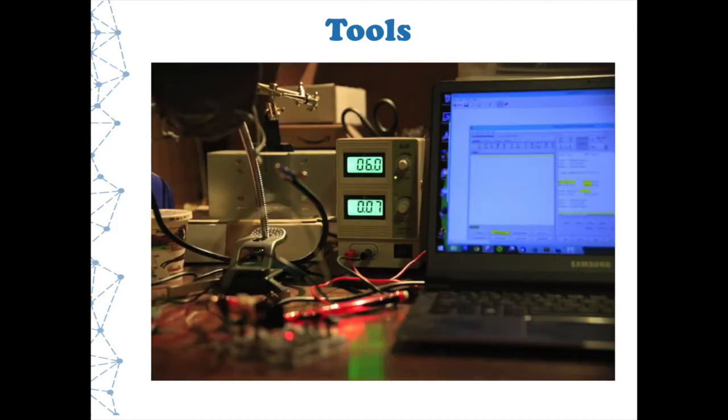Things like a variable power supply, all these little things, they're not required, but they help. They make what you do go much faster and give you flexibility that you would otherwise struggle to wedge things under to get just right when soldering. So spend time thinking about how you're set up and ways that you can improve it. This power supply is a $30 or $35 power supply. It's not super powerful, but it goes from 0 to 24 volts or so and delivers about 6 amps. It's a nice, finely controlled tool, so that makes working with little electronic things easier.